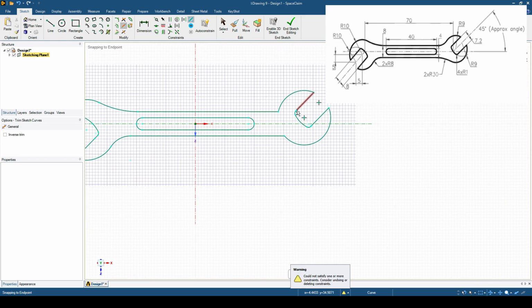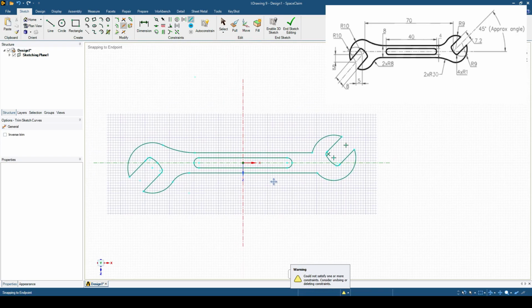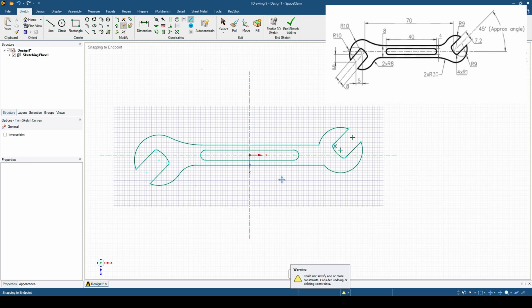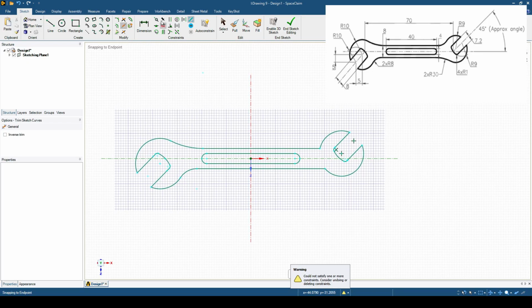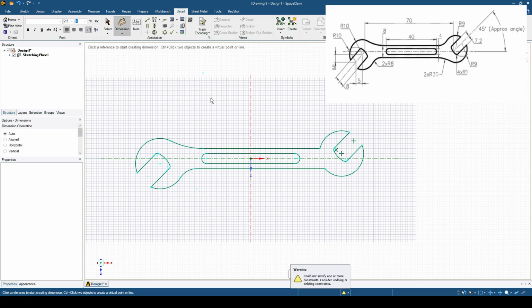So as you can see, we drew this shape with the following dimensions. So now let's try to put the dimensions on it. First of all, we go to detail. I will choose 2.5 as the font size of our dimensions, and then go to dimensions, and now we are ready. So first of all, from this point to this point it's 30, right?